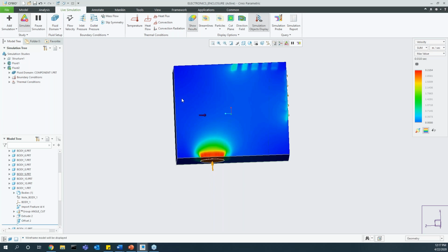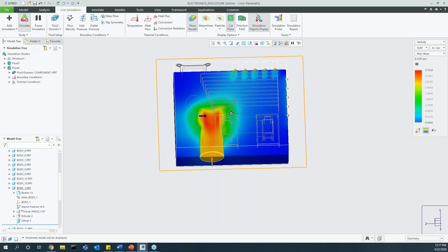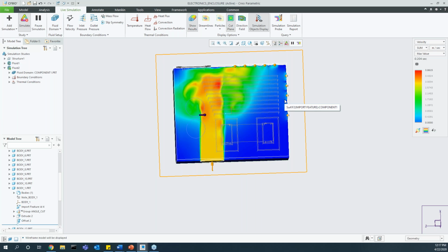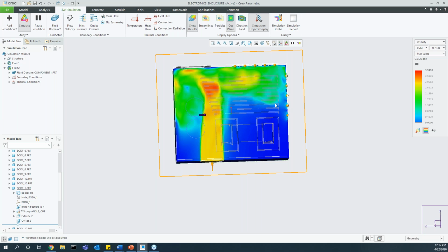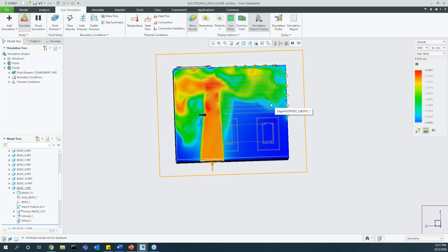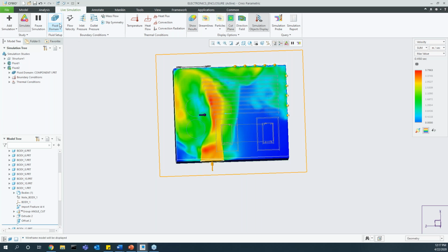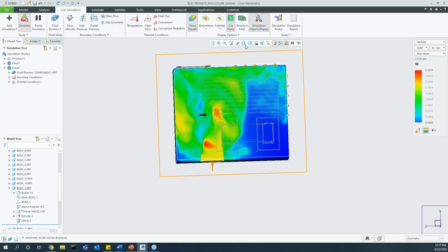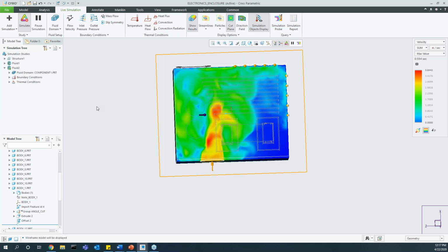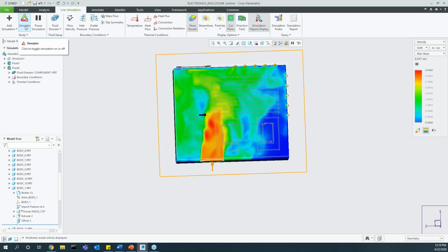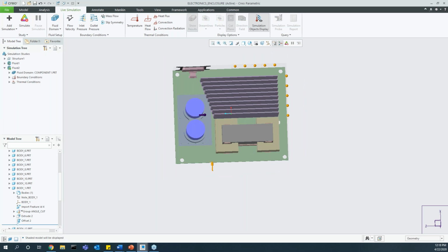Now if I run my simulation and turn on my cut plane so we can see the internals, we can see how the flow gets around here. You can see some higher flows get towards the back here, which is maybe what we're looking for in this design. This live simulation, this real-time flow, allows us to see how our changes are made in real time and tells us the direction we want to make our changes, like Shay said earlier. So that's an internal flow example.